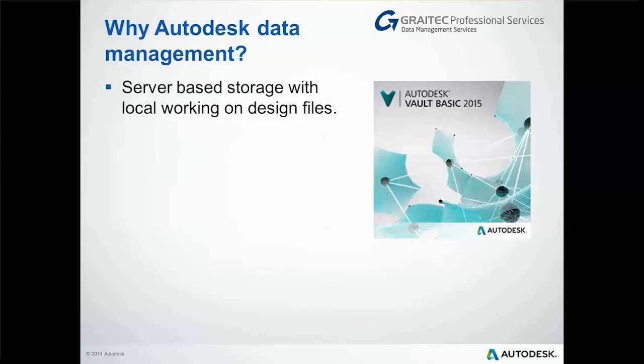So Autodesk Vault is a server-based storage system. So you have a machine that holds what we call Vault Server, but users actually work local to their machine. So a user would connect to the Vault Server, download the file they wish to work on, work on it locally and then upload it. What this means is your network isn't constantly being used. So if you currently find that you're working over the network and it's slow, it takes time to save, you lose data, your network often drops out, we have network issues, this will help alleviate it because users work locally then upload. So there's less activity and traffic.